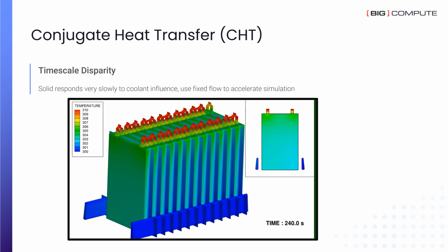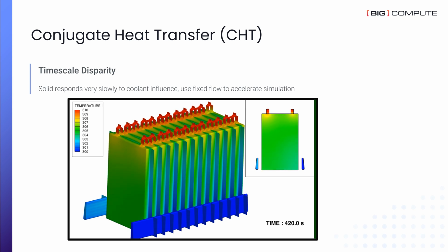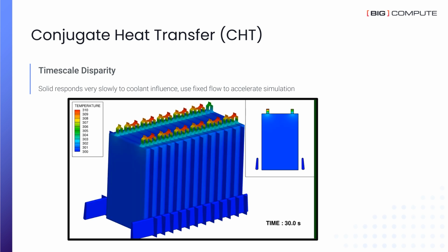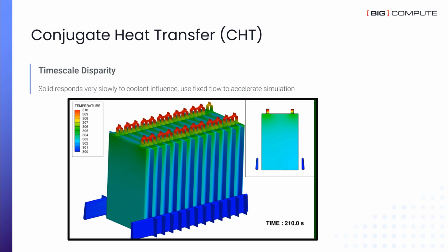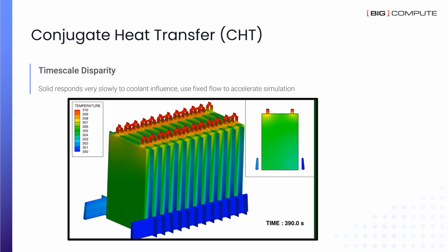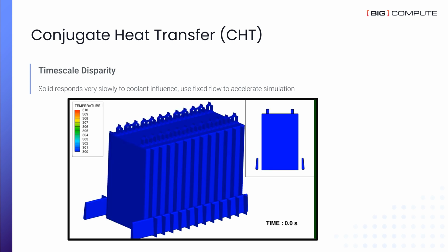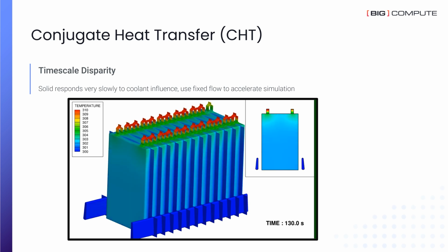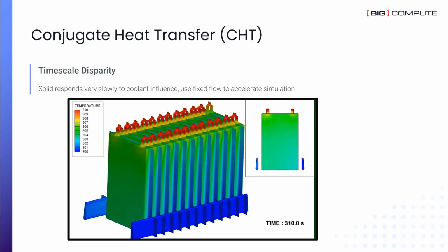This is just a warm-up simulation, meaning we run current through the battery pack, and there are coolant passages on the left and right, coolant supply on the right, coolant return on the left, and there are thin fins in between each pair of cells that carry the coolant between the batteries and carry some of the heat away.